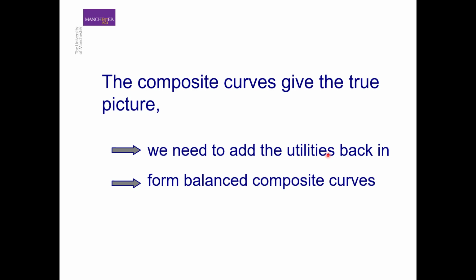So the balanced composite curves give us the complete picture. We need to add utilities back to our composite curves to form the balanced composite curves, and to actually show exactly where our utility pinches are in relation to our process pinches, as I explained in the previous slide.